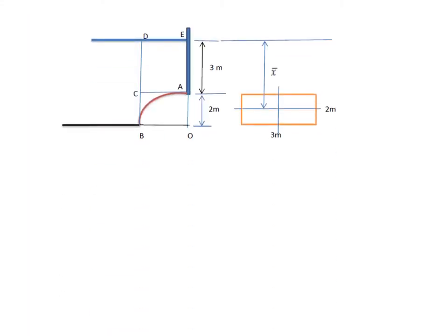So how to find the FV? Here it is nothing but the weight of the liquid from the curved surface to the free surface. In order to find the weight, it is specific weight into volume. But volume is nothing but area into length. So now I am able to find it, because it is acting directly on the surface.